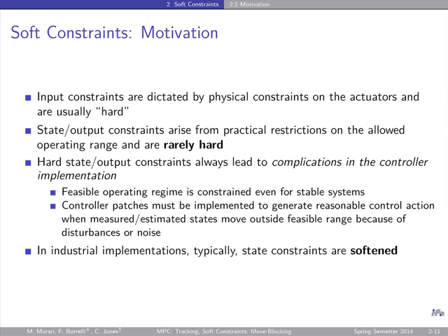Okay. Are there any questions on that? So that again is something very practical. I've given you some theoretical foundation of how to choose the penalty, but this is what you do as standard in industrial MPC algorithms. Because you don't want to deal with the situation of "I'm outside the constraint, what should I do now?" You don't want to have a controller like this. This doesn't happen once you soften the controller in this way, and it will tend to bring you back into the unconstrained region, as part of the algorithm, not as part of a patch you put on top of the algorithm.